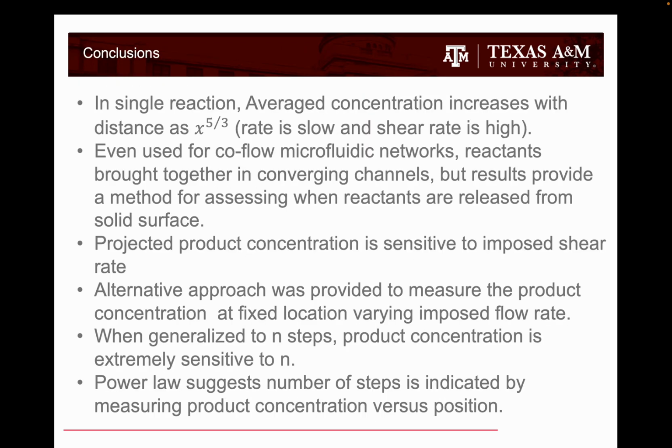So as we come towards the end of this presentation, we would also like to put some concluding remarks here. In a single step reaction, we have seen that the average concentration increases with distance with x to the power of 5 by 3. This comes with the assumptions that the reaction is really slow and the shear rate is very high.